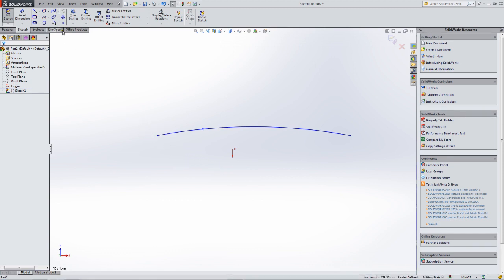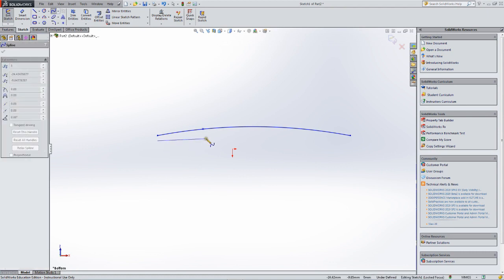So now to draw the bottom of the airfoil, I select spline again. I'm going to keep it a pretty slender airfoil, so I'm going to stay real close. And of course, if you were actually drawing an aircraft that you had defined either by a sketch or in the JET software, you would know how thick the airfoil had to be, and you have specific dimensions. I'm doing this sort of ad hoc without specific dimensions.